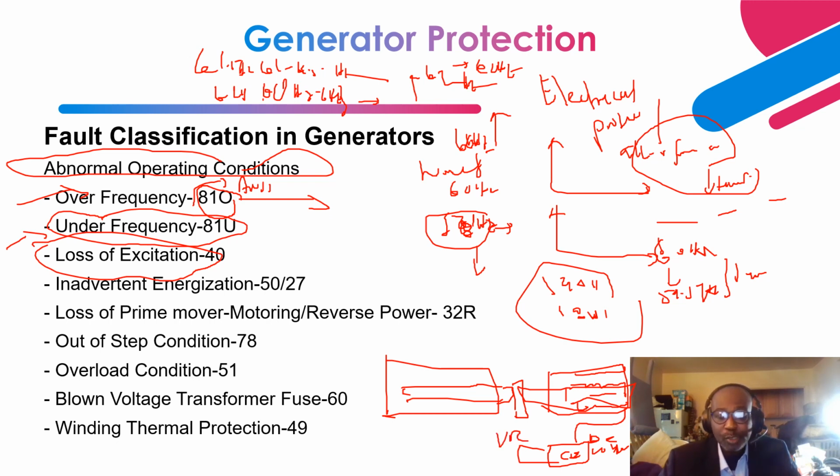What this voltage regulator does is it measures the terminal voltage and current, and based on a feedback loop, provides the signals to the excitation system and the turning on of the rectification system to provide the required DC current to be fed to the rotor winding to set up the required magnetic field to produce the required reactive power that will basically regulate the terminal voltage.